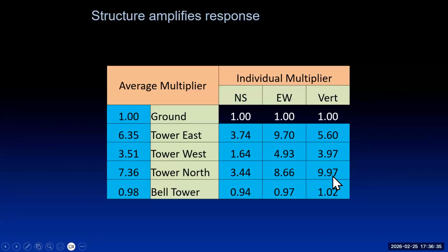To get that, what we did was measure the PSD, power spectral density of the response, and that gave us a 10 times factor. But if you looked at individual time histories, you found anything up to a value of about 12 larger than the ground value of the response.